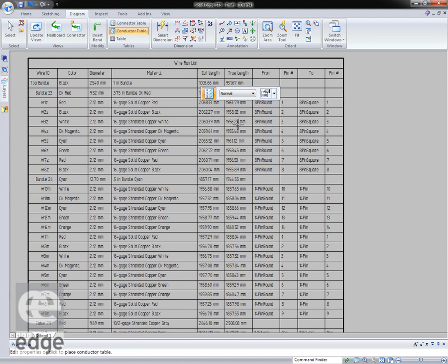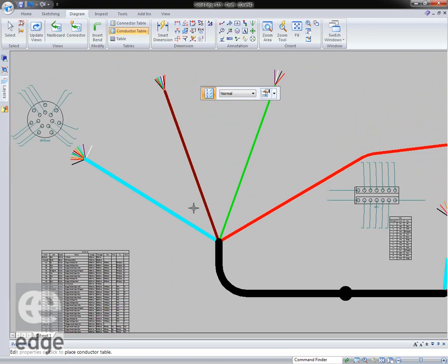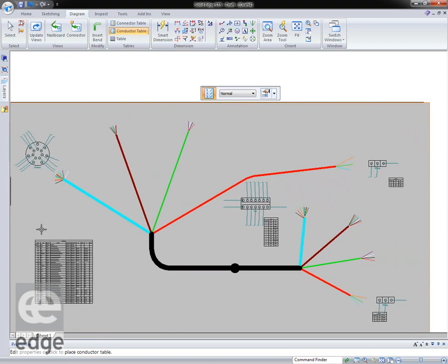So we can have the cut length, and we've got a trimming allowance and a stripping allowance and things on them. So we can pre-cut all the wires to those lengths, run them into the nail board, position nails on our corners so that it fits around there, and just string all the wires through. So we know that that orange one there goes through to wherever the orange one comes out here. It'll tell us on this wire list.